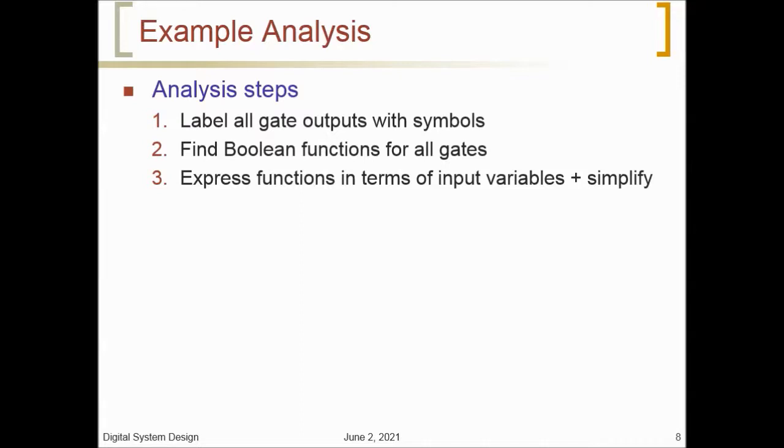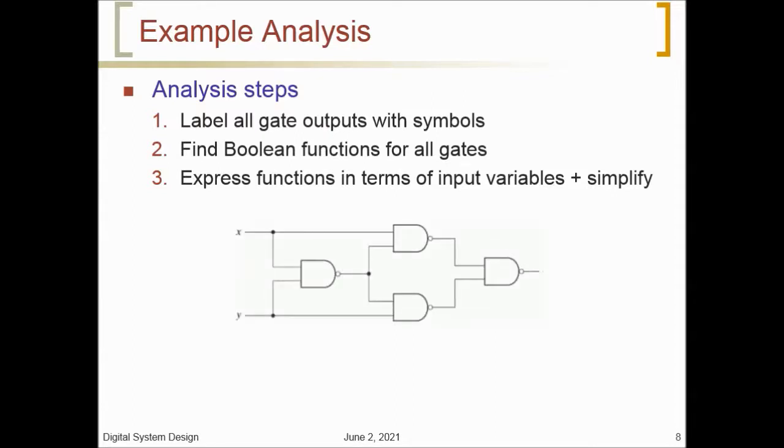By repeating substitution of previously defined functions, obtain the output Boolean function in terms of input variables. The analysis of a combinational circuit of this figure illustrates the proposed procedure.